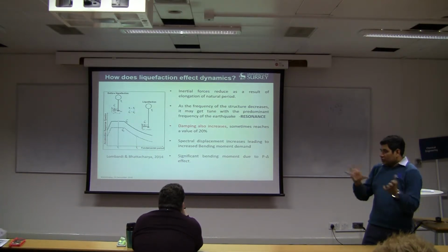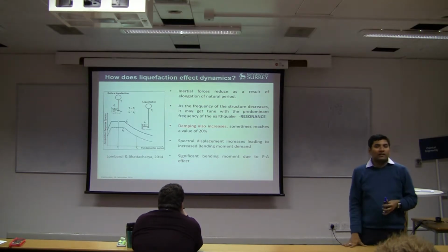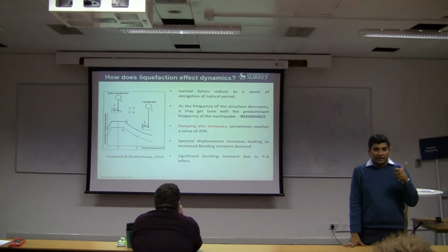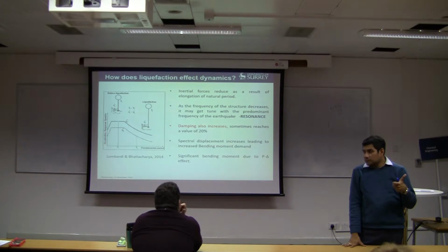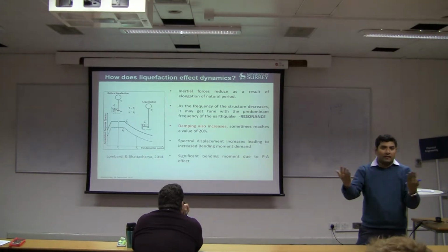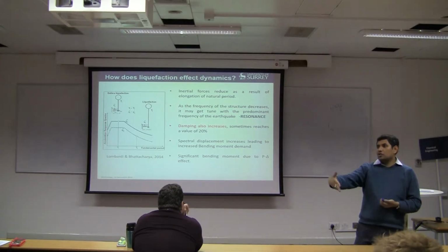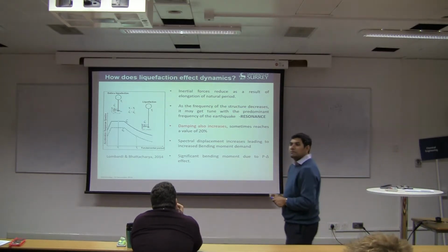Okay, this should be adequate for your overall foundation design. The important thing is the depth of liquefaction. Once you get the depth of liquefaction, then you can think about the different scenarios of failure, and you have to show how things work.